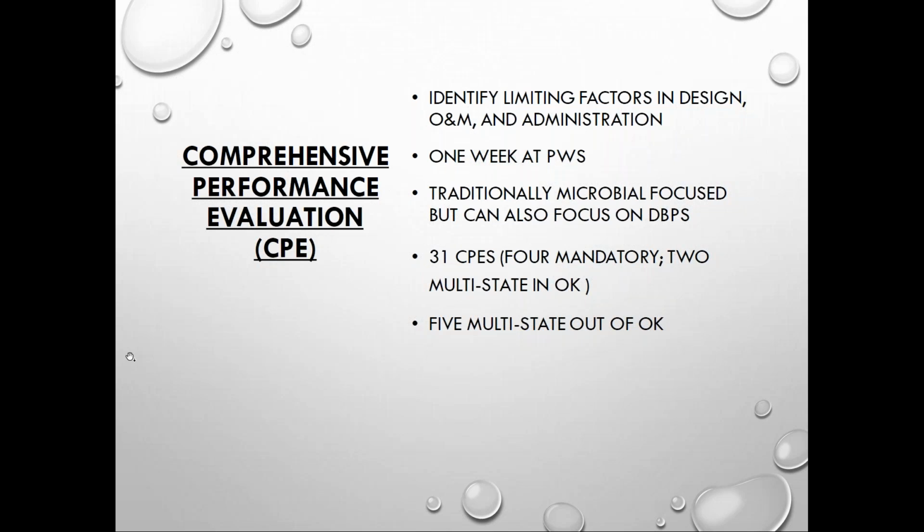As you can see here, it says you spend a week at the public water supply. That's the main part of the CPE, but you do collect data beforehand and even do a pre-CPE visit, and there's a report to write afterwards. But during the week you're at the plant, for Oklahoma, we spend the first day with an entrance meeting and a plant tour. And we spend the next 3 days doing things like interviews and special studies and various evaluations at the plant. And then we do an exit meeting that final day. Some of the special studies we look at include chemical verifications, data integrity for turbidimeters and chlorine analyzers.